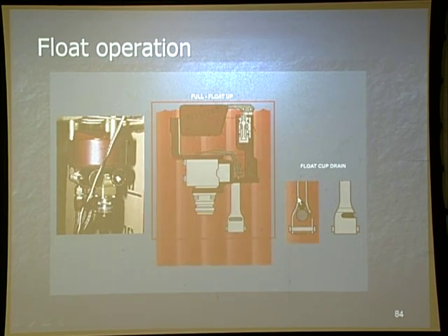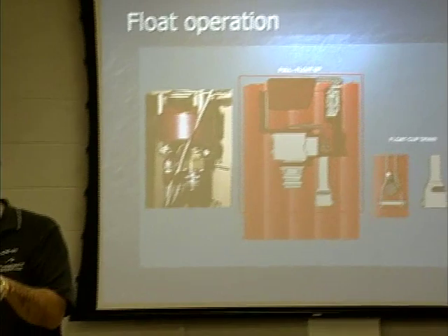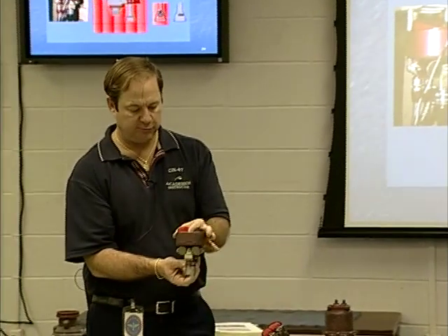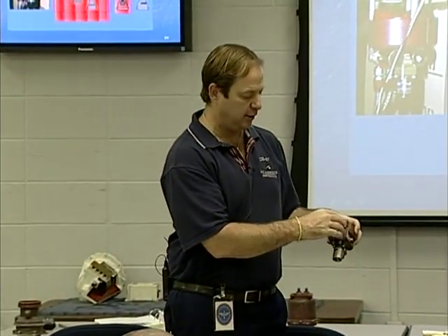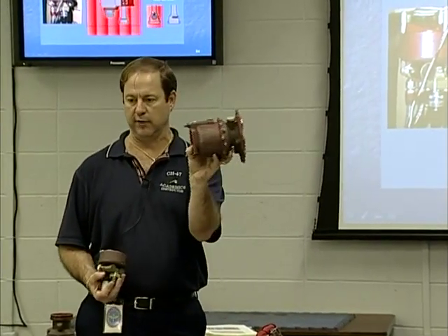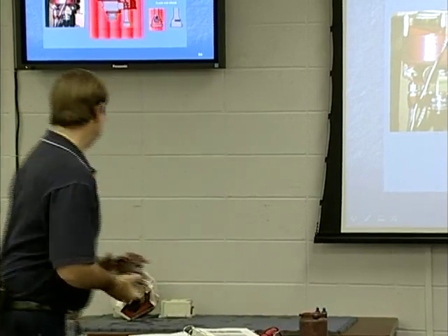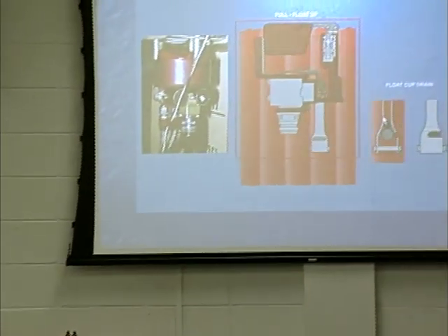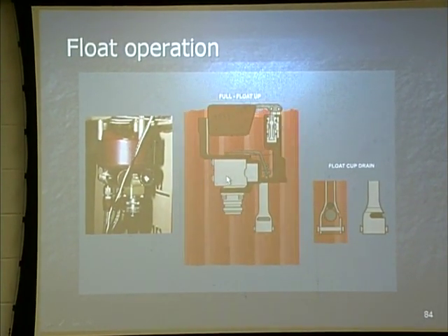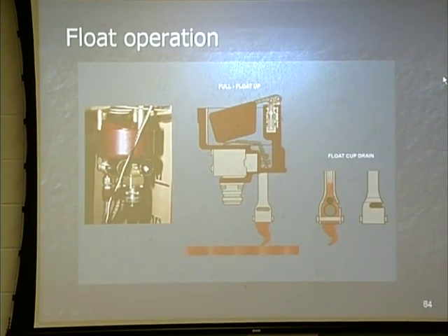Now, here's the 2 floats. You got a big ball, big red ball, and then a white ball in here that seals it closed, and then that fuel's allowed to overflow it and fill the bowl. Floating this float up, which is going to close a valve inside of here, causing a back pressure that's actually going to result in going back here and closing this valve. And this is the one that's in your main tanks. So as fuel comes down, ball's going to be open, allowing that fuel to come back in.